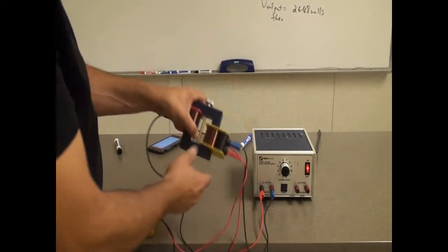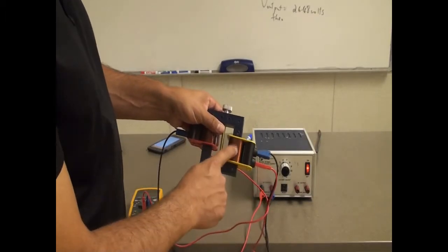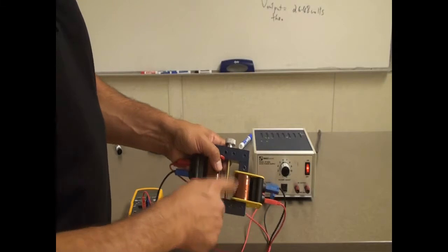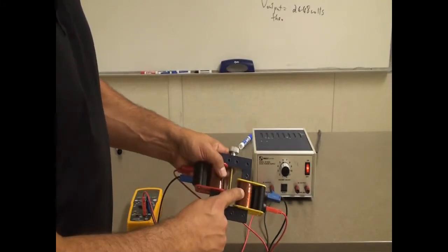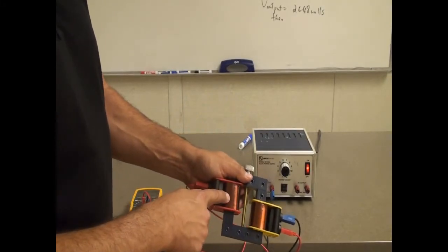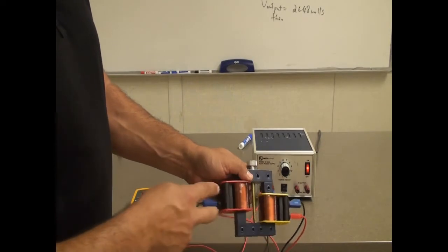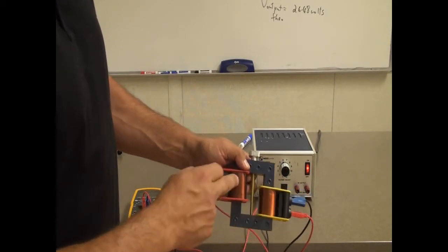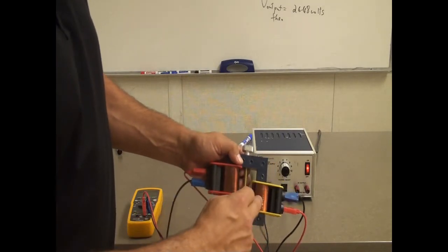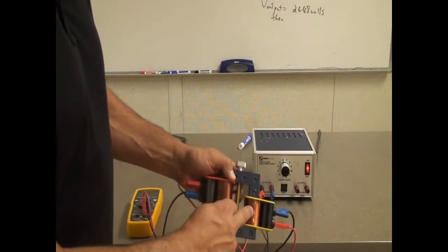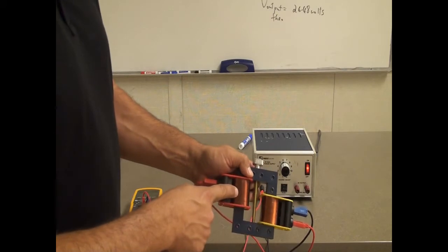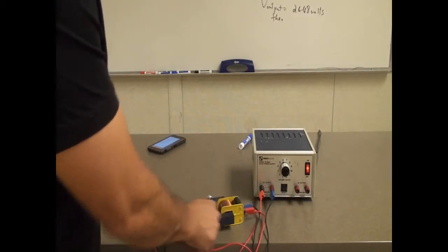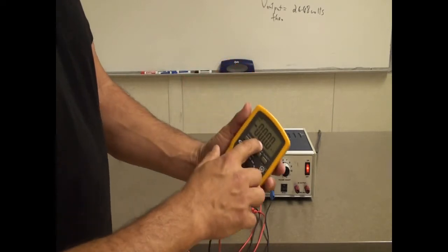Because what happens is the incoming current that is in here creates a magnetic field, but that magnetic field is not changing. Therefore, it doesn't create a current here. And if it doesn't create a current here, the voltage across these two is zero, right? The only way that this can create a current here is if the magnetic field created by this changes. If it changes, then it creates a current here, which means there's a voltage difference here. So you can tell here, 0 volts.